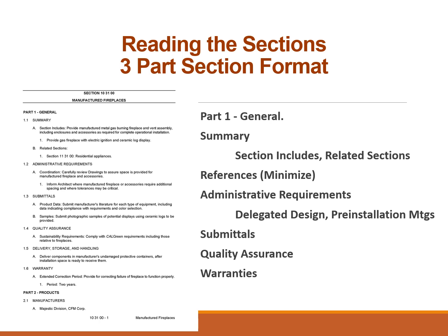Administrative requirements like delegated design, also sometimes referred to as design build, pre-installation meetings, coordination requirements between specific sections, such as you might want to have under administrative requirements for the wood door people and the glazing people to coordinate to make sure they get the glass for the wood doors installed in the site, but coordinated so they know what the sizes are.